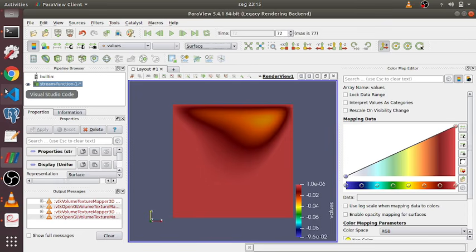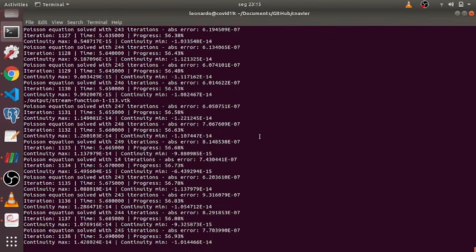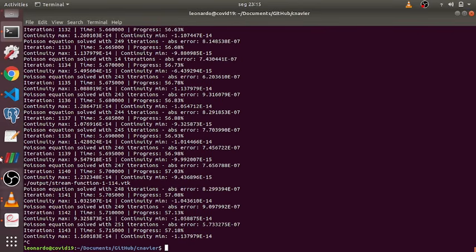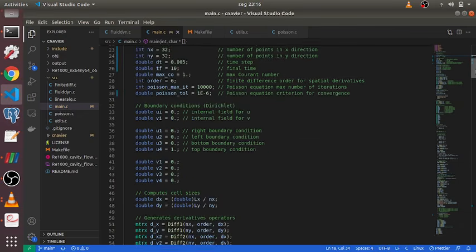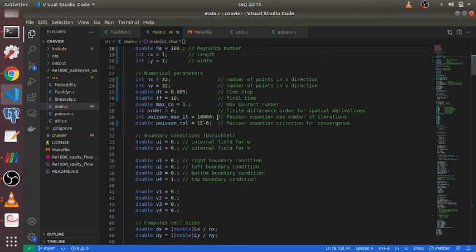In order to solve this, we should decrease the tolerance here. So let's press Ctrl C here and then adjust here. Let's take it to, I don't know, -9, and here we can increase to perhaps 0.01.